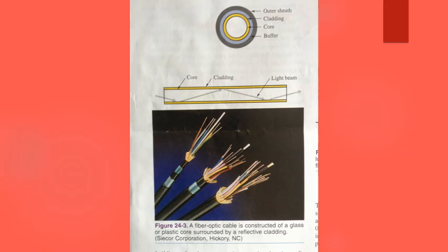The cable sheath is similar to the insulated jacket on typical conductors. The outer sheath construction and materials used depend on the environment in which the fiber optic cable will be installed. Some sheaths are designed to be oil or water resistant. Other sheaths are designed to be installed in salt water or buried directly in the earth.